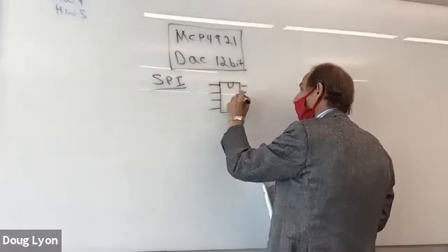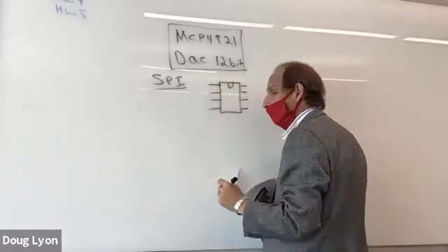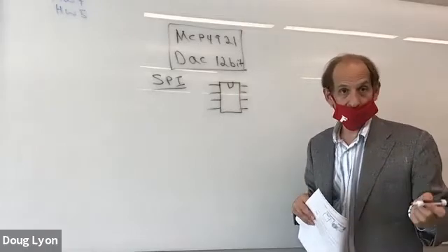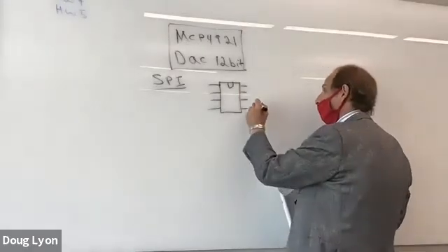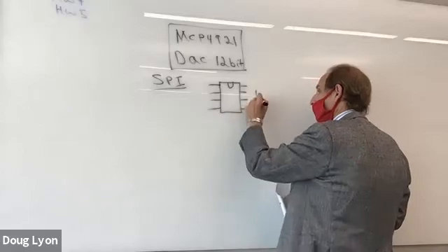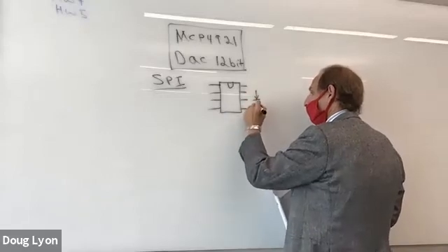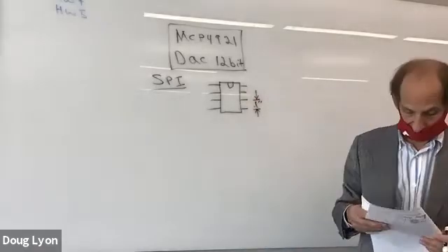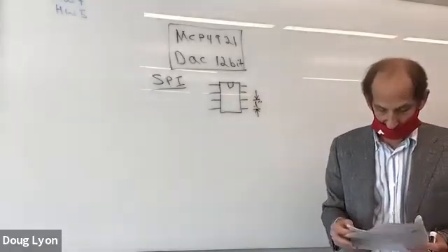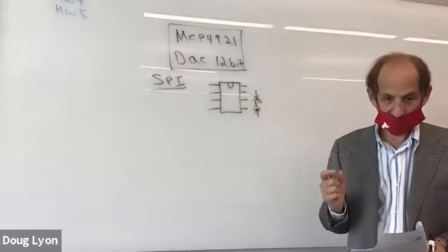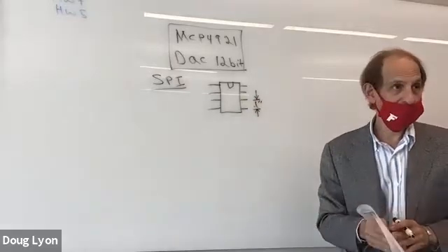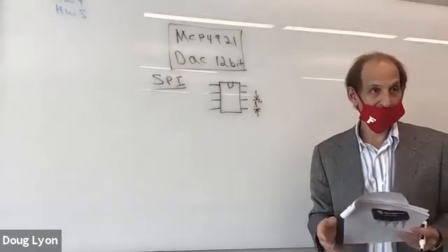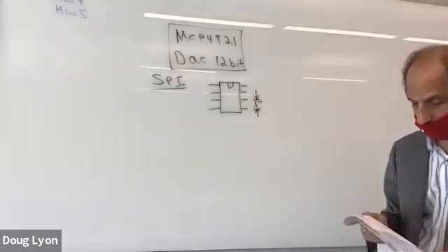It has 4 pins on each side, and the pins for all the DIPs that you will find in the stock room and this one are spaced by 0.1 inch. And what that means to you, the student, in this class is you can take the chip and plug it straight into a breadboard and then hit it with the DuPont wires and wire it straight to your Arduino, which is very convenient.